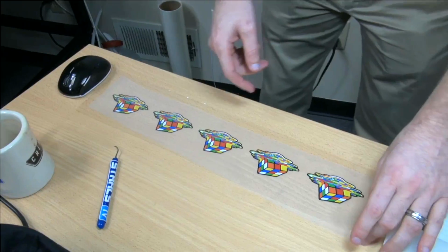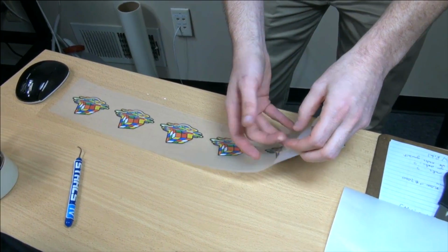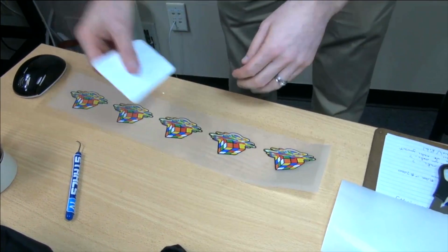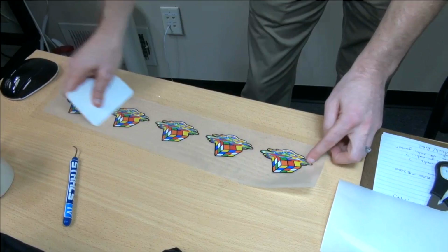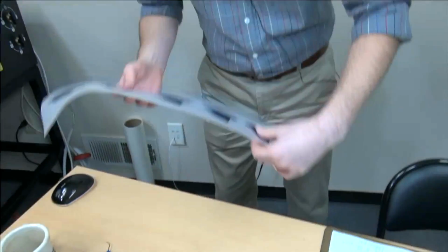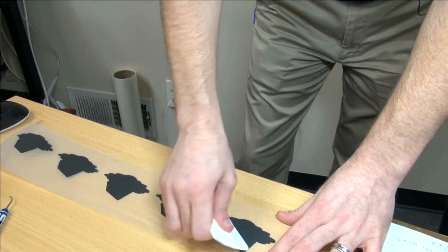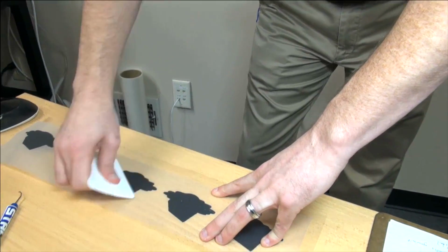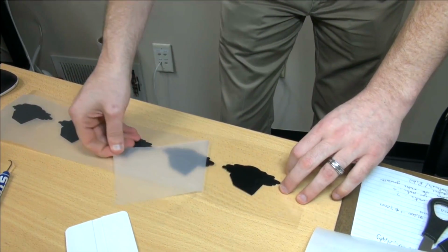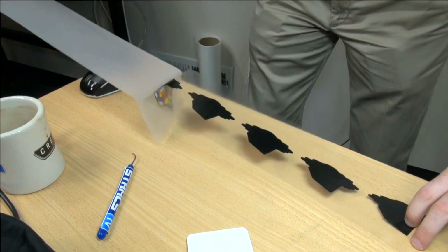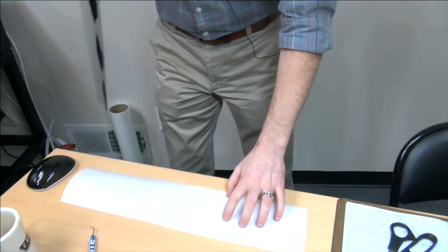So we've laid down our mask, which is just a sticky material. If you buy CAD cut material now, this is the sticky material that's applied to your CAD cut. And we're going to use a squeegee just to push the mask down onto the graphic. I'm going to flip it over. I find this works best with this particular material, to flip it over and peel away. I pushed hard enough there on my edges. Okay, all right, so you can hear that. And I'm saving the back of the mask to put these transfers back down onto.